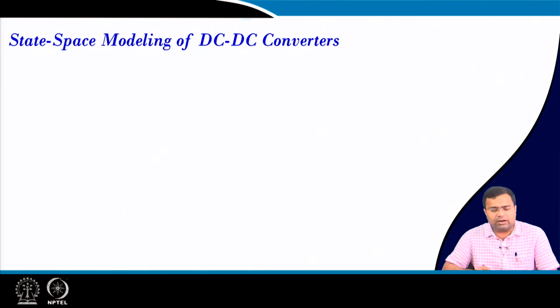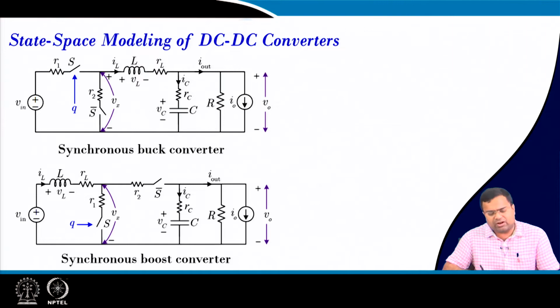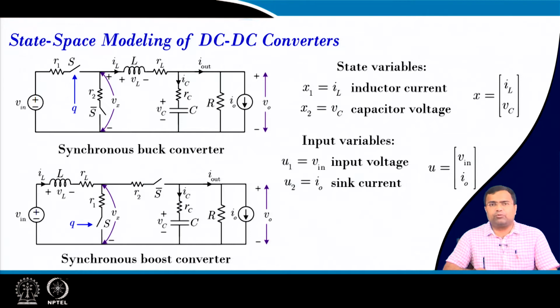So, if you recall, state space modeling of DC-DC converter, if you take a synchronous buck converter with practical parasitics, and we can also consider a synchronous boost converter, where we can consider inductor current and the capacitor voltage as the state variables, and we can also take the input variables as the input voltage and the load current if we consider an additional sinking load.